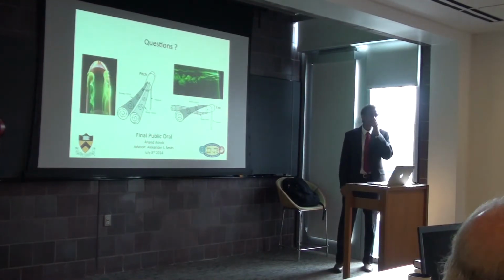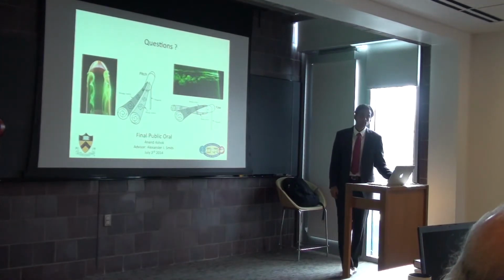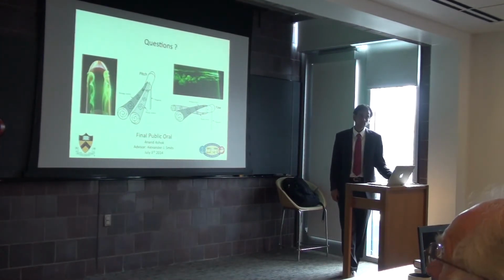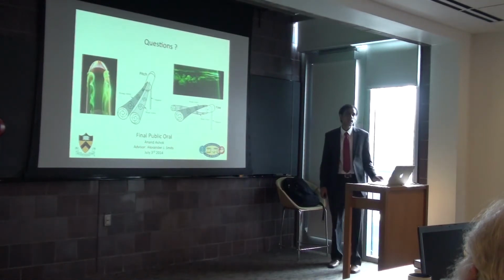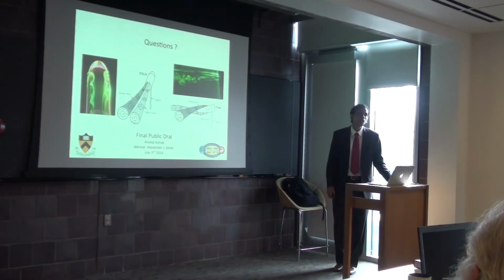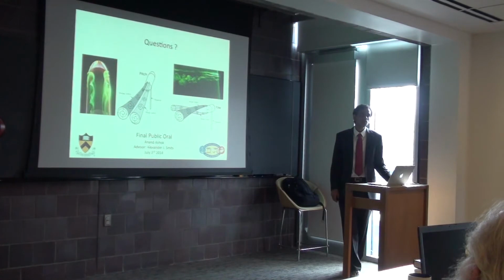Tyler. I was going to follow up on that too. Do you think it's possible that it's because of surface irregularity? Because there's a total runout inherent to the cylindricity of what you have machined. So that's what the surface roughness perturbation study that I did attempted to address. Right. So there's a difference between surface roughness and surface irregularity, right?